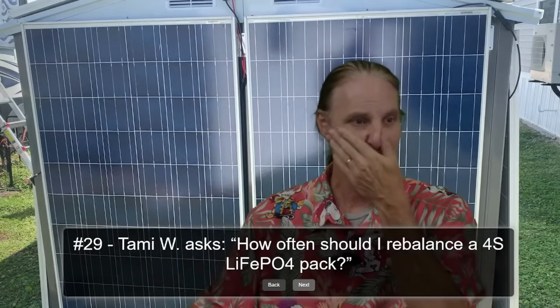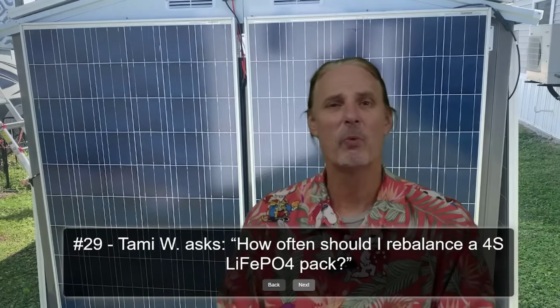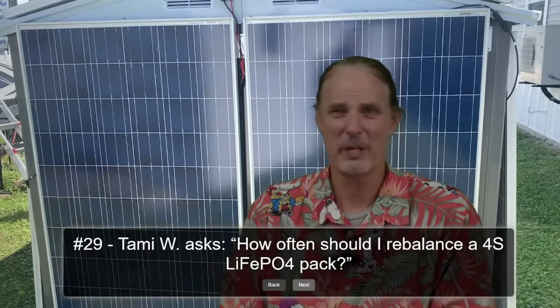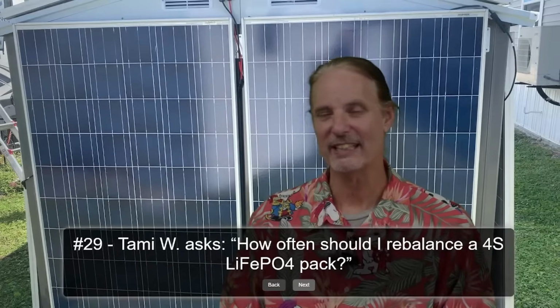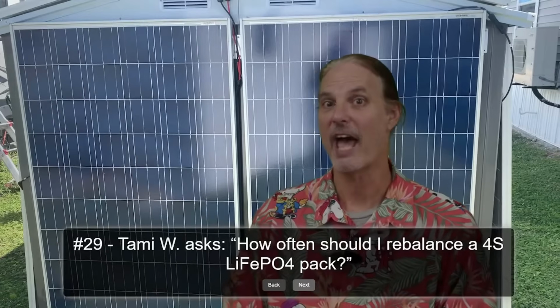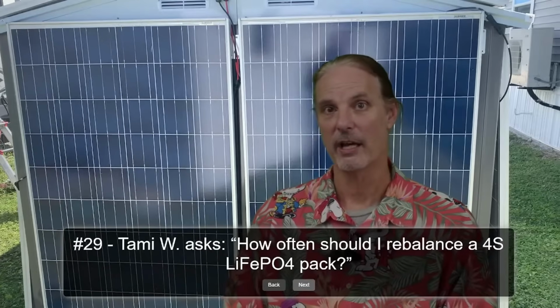So how often should you balance them? I would say a minimum of once a month, I would balance all my batteries. Is it an absolute necessity? No. I went 3 months just recently without connecting any grid or doing anything, based on the extra power the solar shed had provided me and based on adding the new 15.6 kilowatt DIY solar battery.